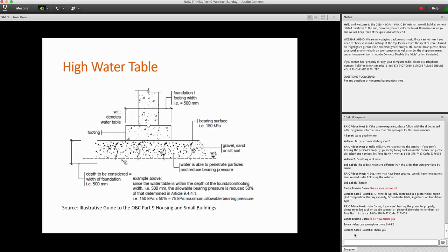So let me just say, again, this is a case where the water table is below the foundation. Again, if the water table is above, you do need to have structural design for a floor slab that can help resist that uplift that would be caused by the groundwater. Or to avoid the problem entirely, shift the bottom elevation of the foundations upwards and always build above that water table. And information on that can also be found from the local municipality, any conservation authorities. It's quite common that they would understand where the floodplains are and high groundwater.